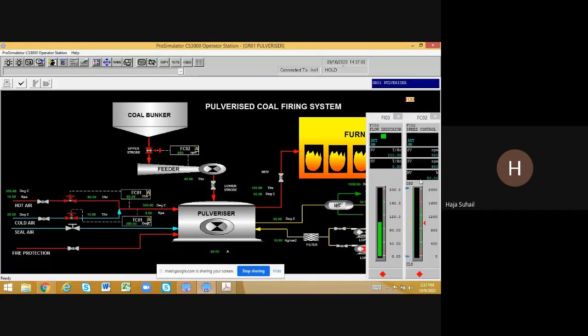It is the signal given to the valve which is connected here. You can see the PV is measured on one side, and whichever signal is going to the valve goes through the MV. Whatever value we have to give, we give it in the SV first. So this is the actual difference between the controller and the indicator.